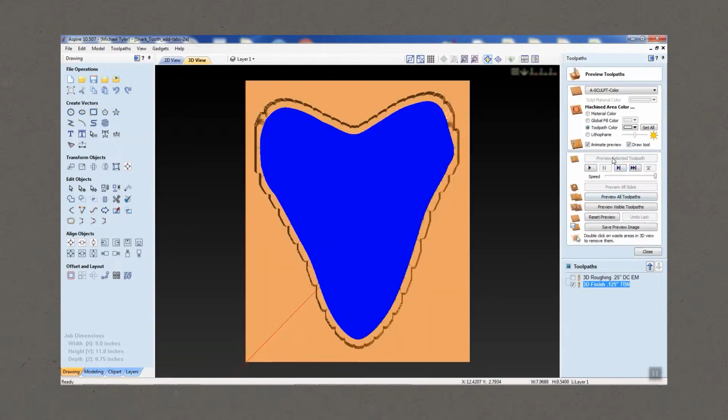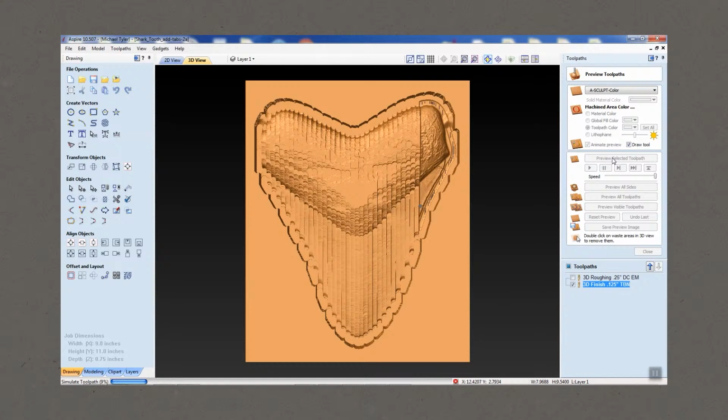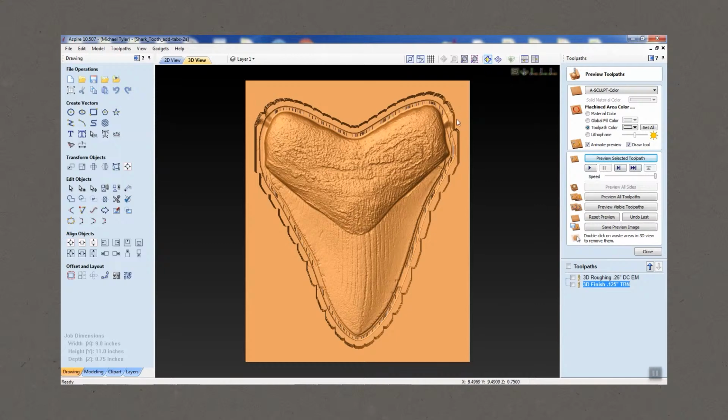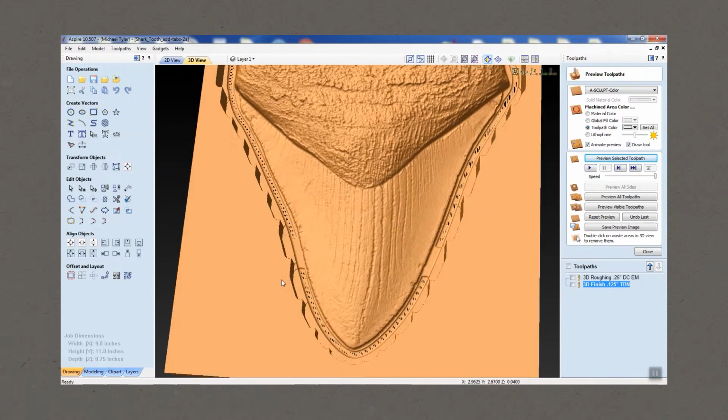Okay, now we can preview the finished tool path. And as you can see, it's got these little kind of funny black lines there. That just shows you that it's a pierced carve. It's actually that tip of that ball nose is breaking the bottom surface of the material here and there, and that's what's represented in this preview. There'll be some of this material left behind because it's not a flat end mill, it's a ball nose, so not all of that ball nose is going to go completely through the material, but this little sort of onion skin all the way around will help hold that in addition to, we got the 2 tabs at the top and the 2 flat tabs at the bottom, although it's kind of hard to see, but there they are.